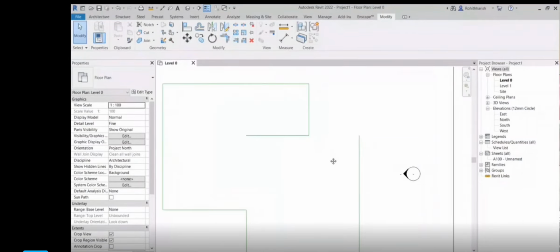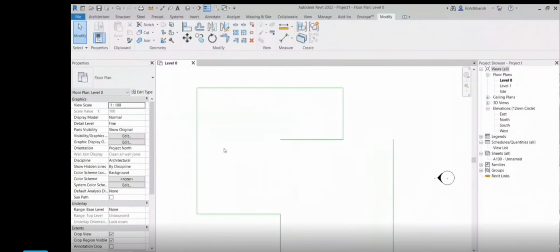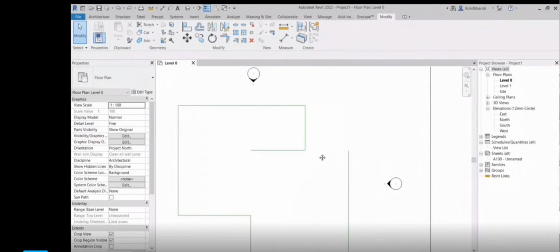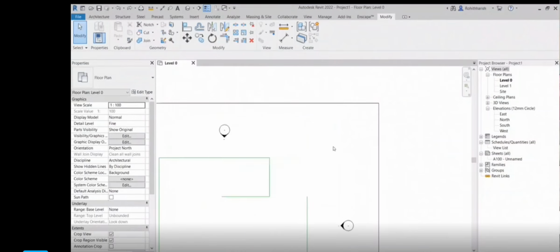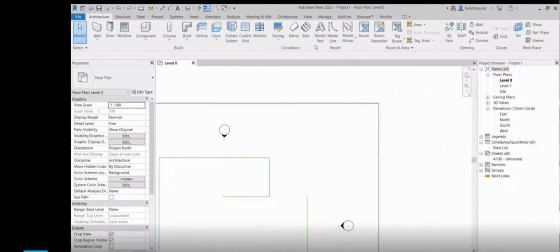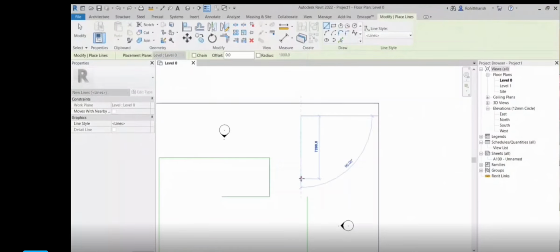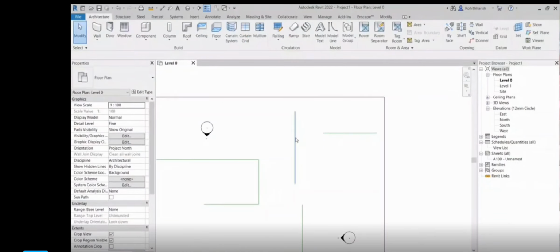See, along with this, if I don't want to disturb this, and if I want to create it individually as well, it will still work. I hope yesterday we did it on Shivani's system. Say I want to extend it till here. Simply I'll go to trim, TR, this and this, and it will extend along with trimming. If I'm working with edges, like the extreme corners, and I want to extend or join this, again I'll use trim and extend, TR, this and this.